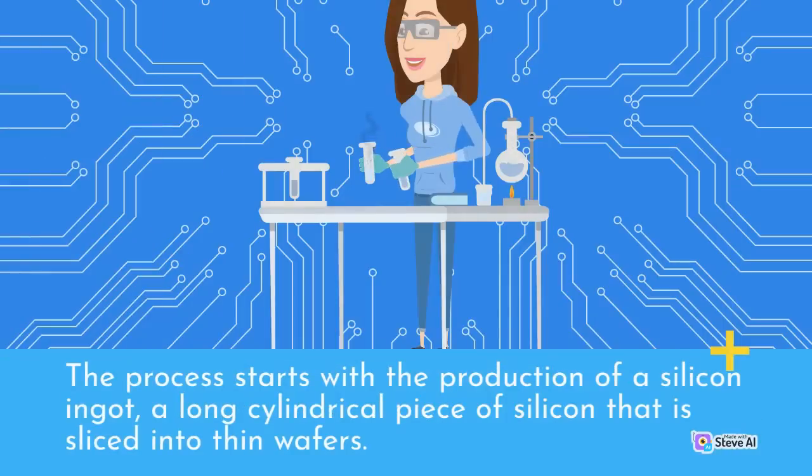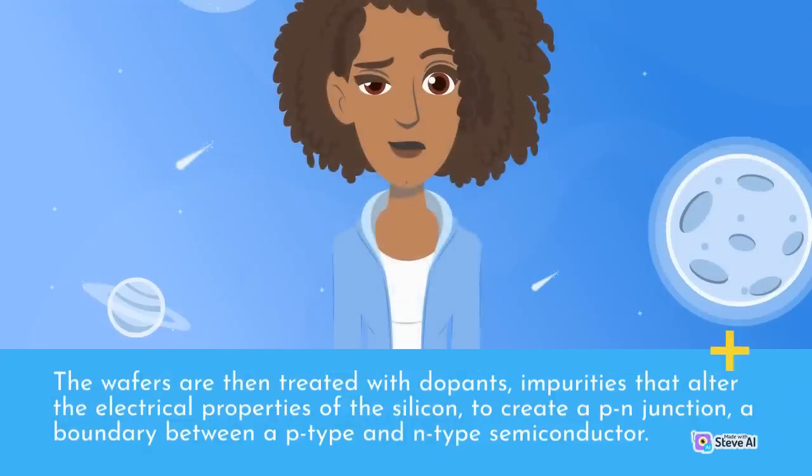The process starts with the production of a silicon ingot, a long cylindrical piece of silicon that is sliced into thin wafers. The wafers are then treated with dopants, impurities that alter the electrical properties of the silicon, to create a p-n junction, a boundary between a p-type and n-type semiconductor.